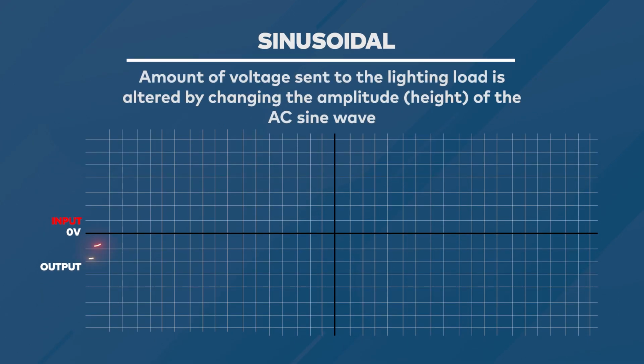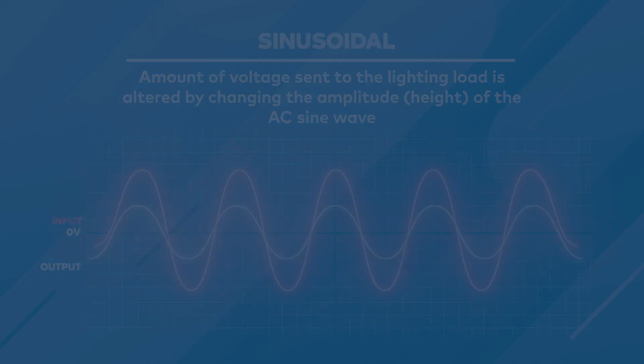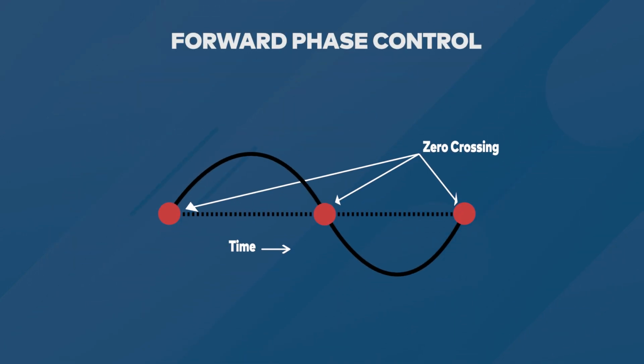An easy method of reducing the light level is to reduce the amount of voltage that is sent to it. By using a transformer with a variable tap attached to a wheel or lever, the overall amplitude of the AC waveform, and hence the voltage, is reduced from full down to none, and the connected device will emit a proportionate amount of light. Unfortunately, this method is very expensive and bulky to build, and has very few methods of remote controlling the level. The next method to control the amount of light is one of the most popular since it can be economically manufactured into a relatively small package.